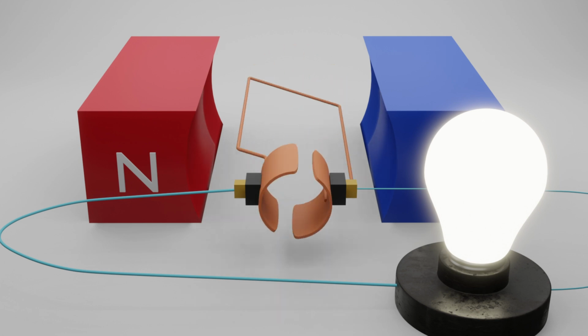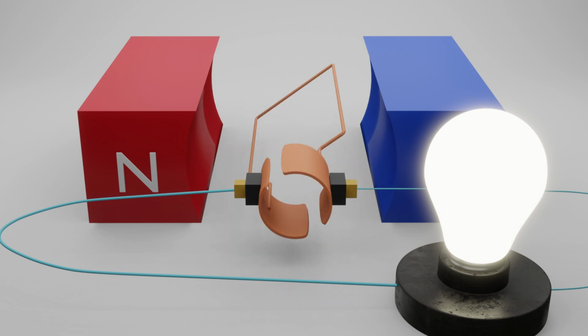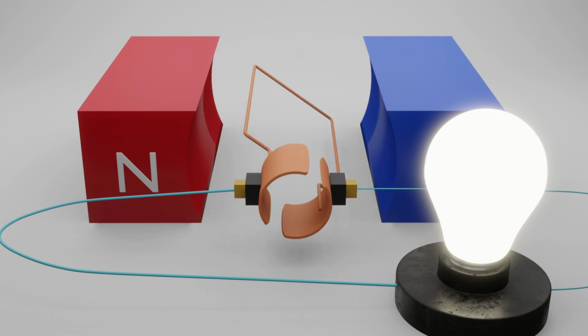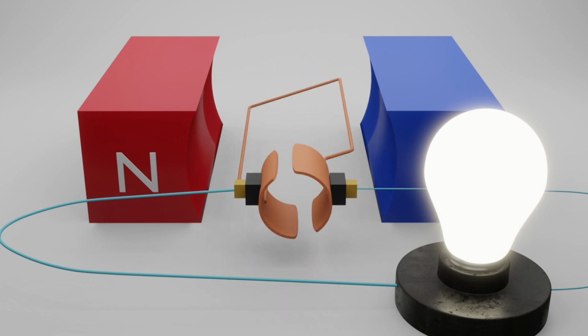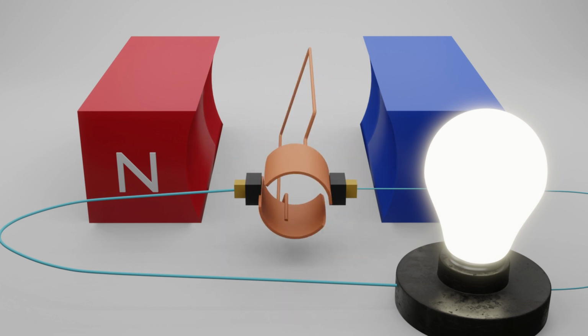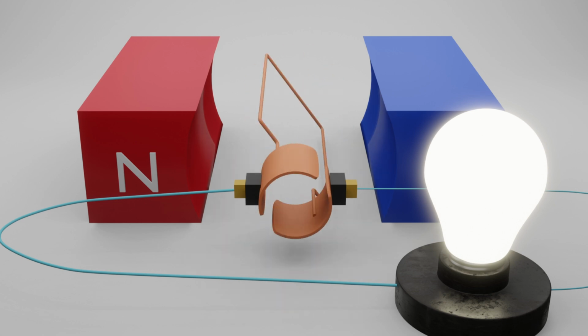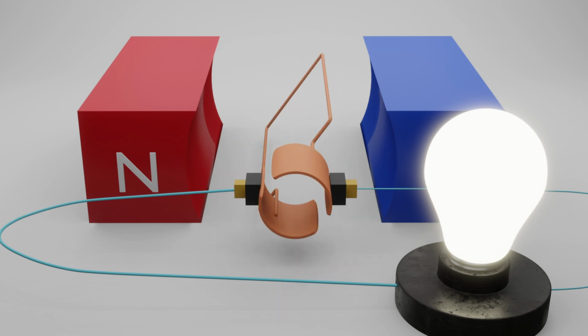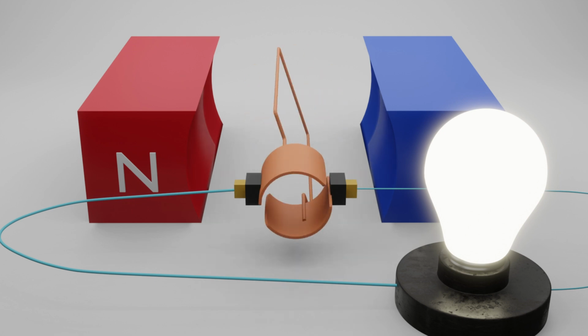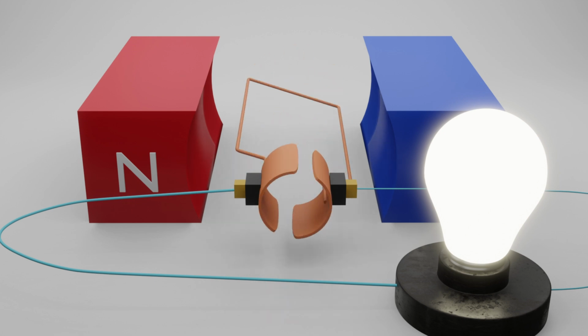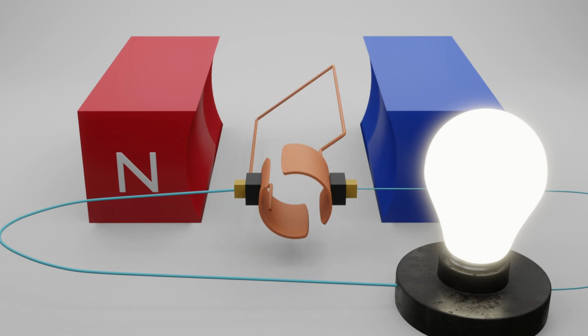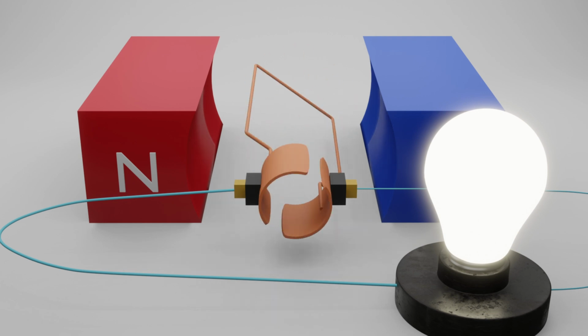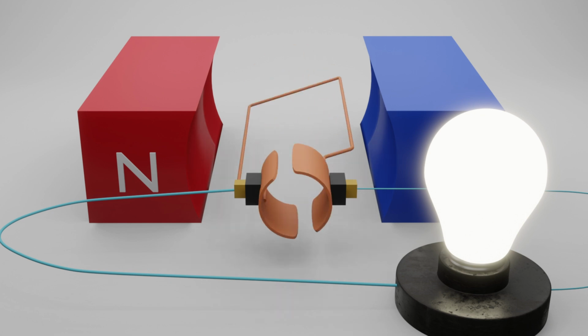Imagine a scenario where a DC generator is running slower than this critical speed. At such speeds, the generator struggles, failing to build up sufficient voltage. This phenomenon occurs because the field resistance line does not intersect with the open circuit characteristic, or OCC, curve at speeds below the critical speed. Therefore, the generator cannot generate the necessary voltage to function properly.